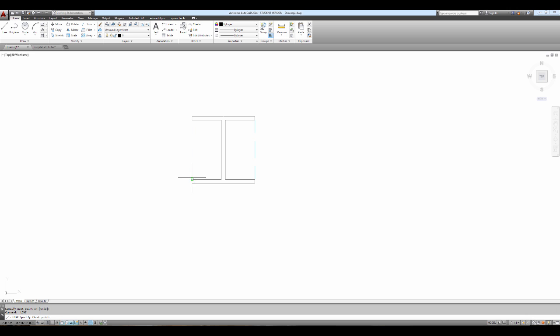So this block that we just drew, okay, I'm going to go ahead and move this away from my 1 inch block now here. So we'll go ahead and select those two lines there, that line, that one. And notice I'm not making a big window around it because I don't want those blue lines as well. I just want my I-beam here, okay?